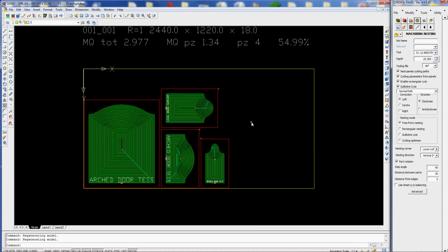as they are there. So we have from one drawing with a parametric geometry using local variables, all of those doors now have come out with the 50mm around the edge and the 120 from the top, and from there we can output the program ready to run. I hope that's helped you understand local variables using parametric geometry. Thank you for watching.